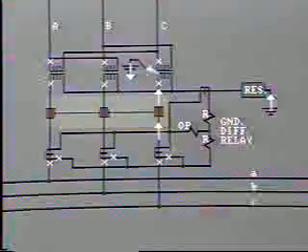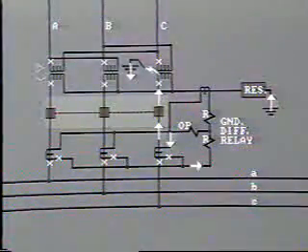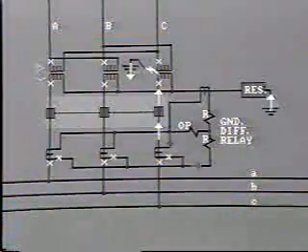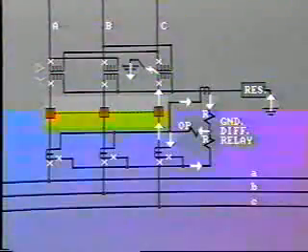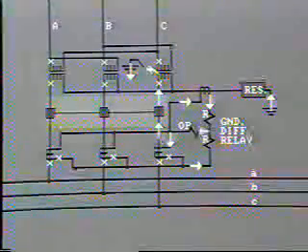But if there is an internal ground fault in one of the transformer windings, the current in that CT will reverse and be added to that from the neutral CT. This current will flow through the differential relay and it will operate.